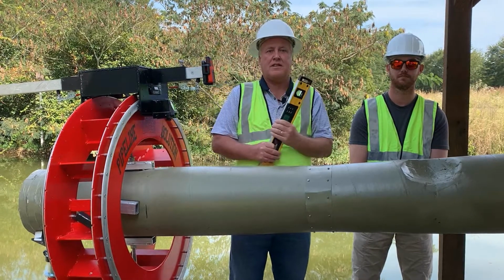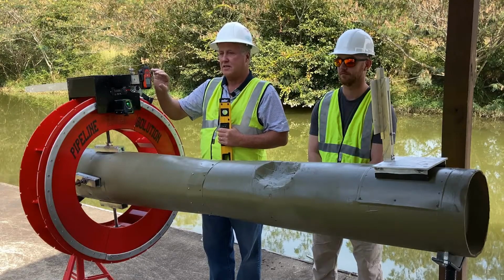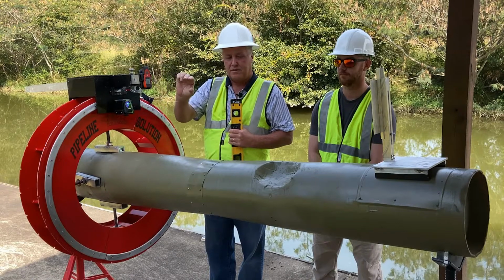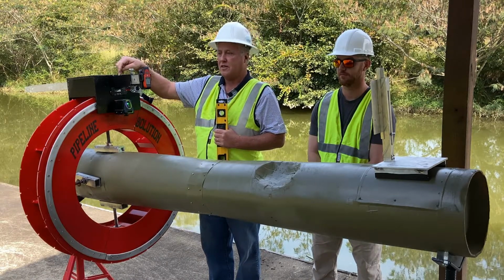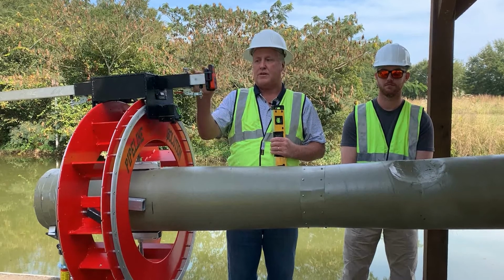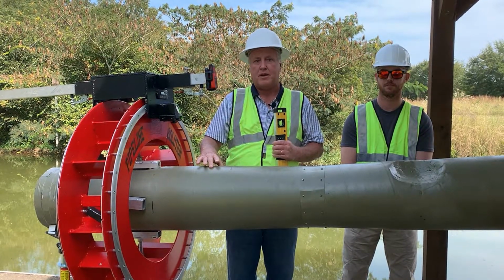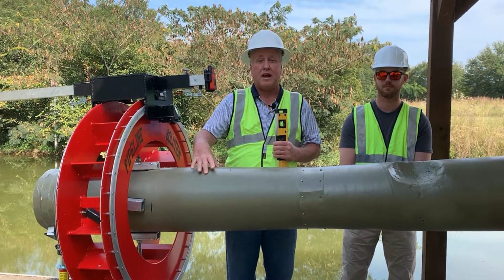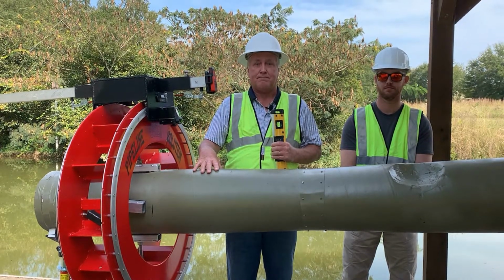Okay, now that we have that set up, let's go ahead and talk about the arm here. It actually extends, and that's what gets the different lengths out to the anomaly. It's 1-inch increments on center. There's a starting point that we start, and the reason we have a starting point outside the anomaly, we want to try to find a place on the pipe that's less than 1% out of round. That way we kind of have a basis to start with.